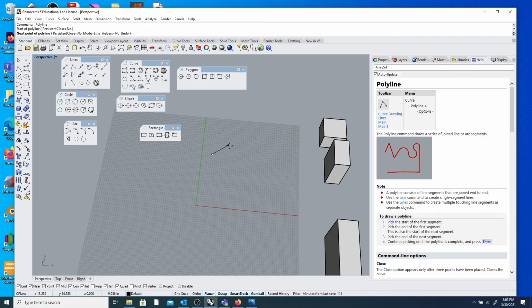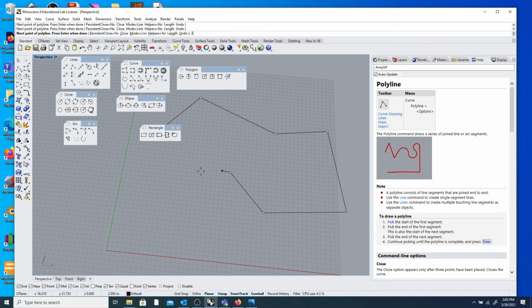So I can just keep drawing, and I can do this without entering information, or I can constrain this line at 2 inches. So I can type 2, and boom, I can't go in any direction further than 2 inches. Then as soon as I left click, I've got this on a rubber band basically wherever I want to put it.